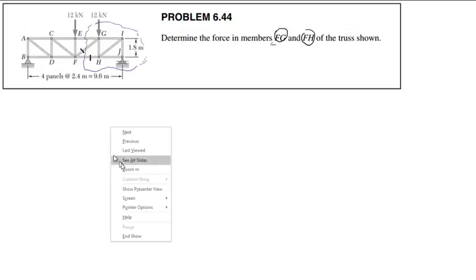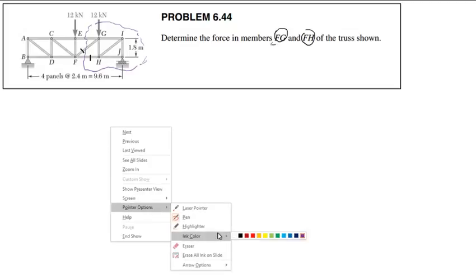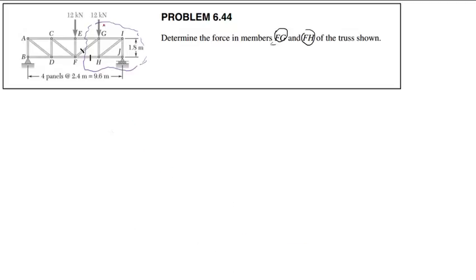How'd you know to cut it in half like that, not just draw the individual triangle from FG to FH? Well, I could just cut out the entire piece, but notice that'll give me a whole bunch of unknowns. I could cut this portion out here, but then that would give me 1, 2, 3, 4, 5, 6. Every time my cut line crosses a member, that's an unknown.